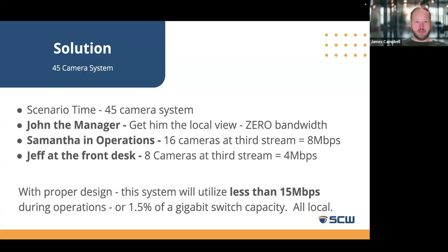And we do have a good question. Wouldn't the local video from an NVR require an extension, or the existence of an HDMI cable, if the NVR is in a rack-mounted one? Absolutely right. So obviously there's two options there: whether the NVR is close enough to get a real HDMI cable, or number two, there are also HDMI extenders out there that run it through a dedicated CAT cable, so it doesn't use bandwidth on the network, but still allows us to have the video and the mouse all across the facility. So there's AV products that we use to achieve John the manager getting access, even if he's across the other side of the facility, basically. But really good question.